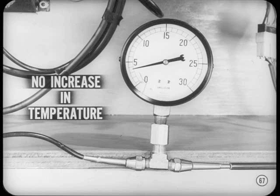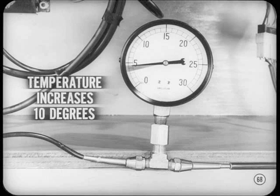Set the external vacuum source to apply 3.5 inches to the water valve. At this setting, there should be no increase in the output air temperature. Start a slow increase in the vacuum supply to the water valve. At 4.5 inches, the temperature of the output air should increase 10 degrees or slightly less. Of course, you'll have to wait a short while for the thermometer to catch up.